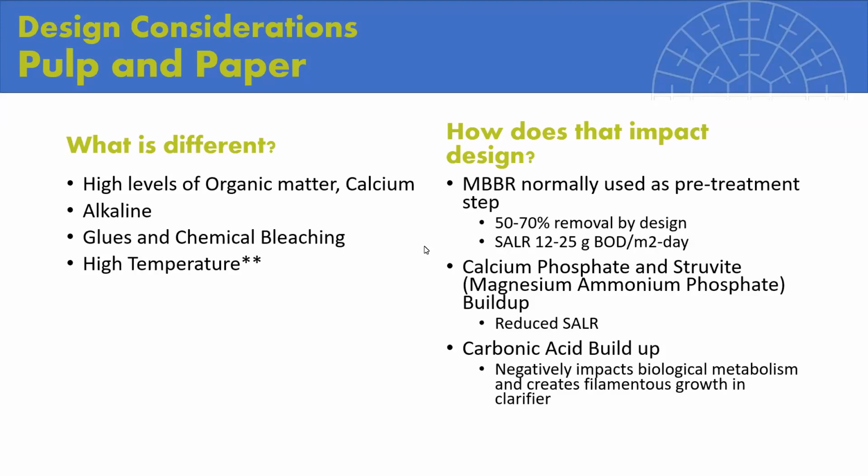Kelsey touched on this. Being able to spread not only the organic load across the media surface area, but also anticipate the spread of inorganic material. If the inorganic material can't be removed in primary treatment systems, then we absolutely have to think about that for the design of MBBR systems. Unfortunately, as Kelsey mentioned, there are a lot of MBBR systems in the world that didn't necessarily understand that. And what you find is that over 5 to 7 years, the media will foul with inorganic material.